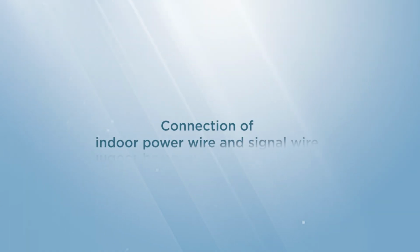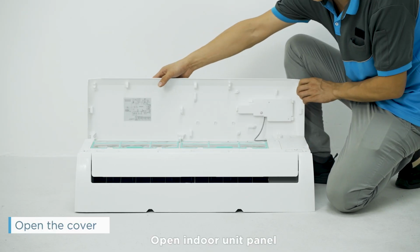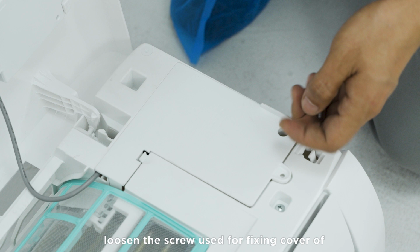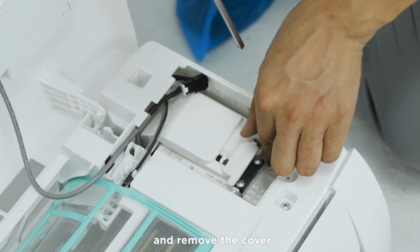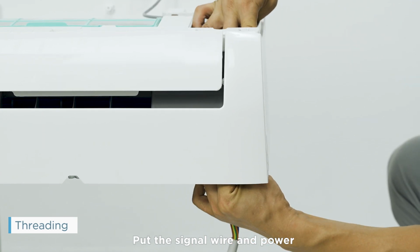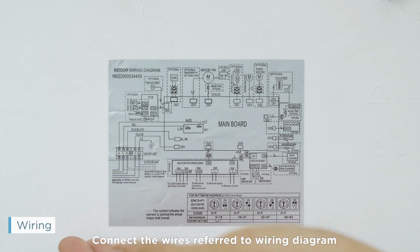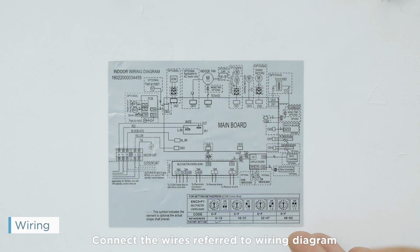Connection of indoor power wire and signal wire. Open the indoor unit panel. Loosen the screw used for fixing the cover of the electric control box, and remove the cover. Put the signal wire and power wire through the wire outlet from the back. Connect the wires, referring to the wiring diagram.